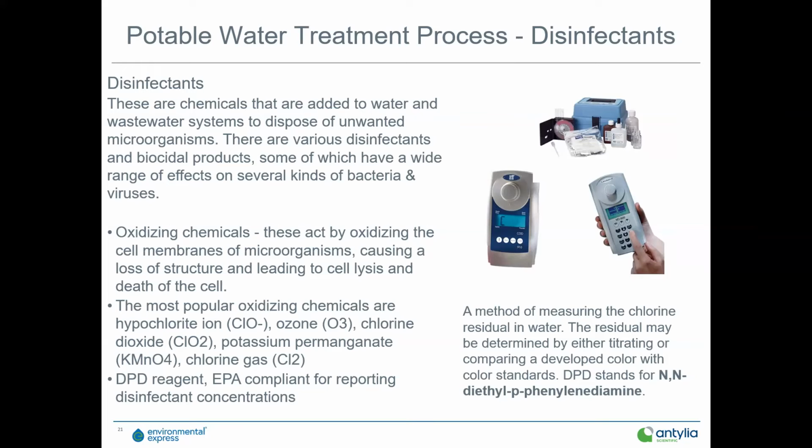By far, the most used, again, in the Midwest is hypochlorite, sodium hypochlorite, which is just your normal Clorox bleach. It is at a lower percentage. I think that Clorox is 6 or 8% hypochlorite, whereas a water treatment plant is going to use the much purer 15% version. Sodium hypochlorite is available, and calcium hypochlorite is another good option.